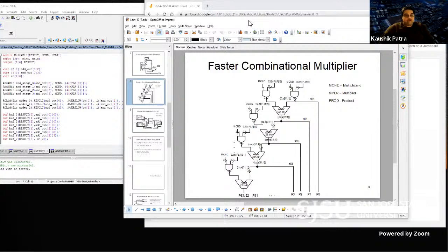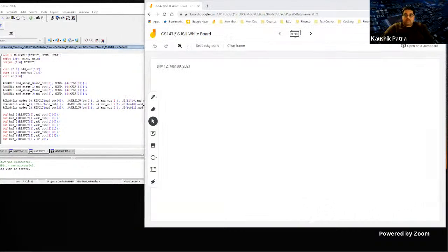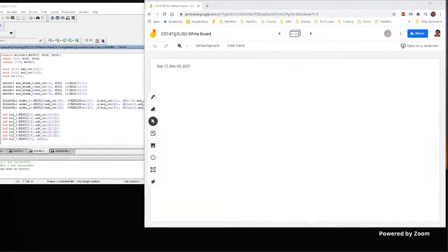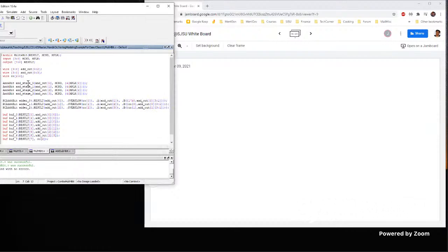I have defined a gate level simulation model, as I'm showing in this ModelSim window, and it is using 4-bit ANDs. Both of the inputs are 4-bit each. Inside that implementation, it actually has 4 AND gates.